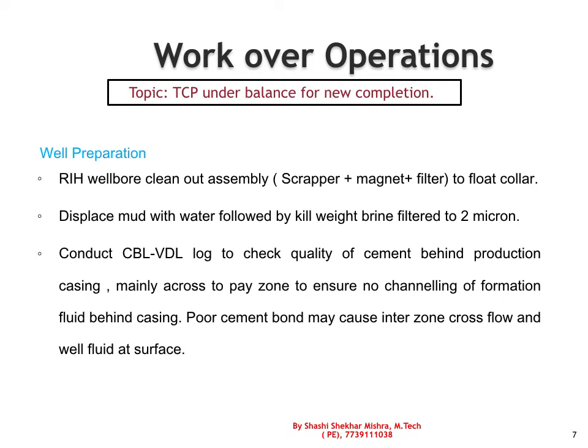So first we proceed with well preparation, and we run the wellbore clean-out assembly, mainly having the scraper, and in the perforation zone we scrape the casing multiple times to clean that part. This is also done to confirm that the bottom of the well is as per design or program.